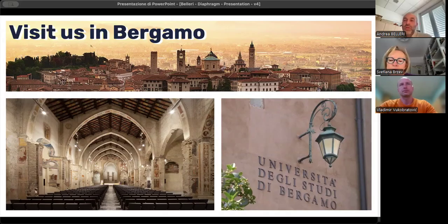Of course, yes, for sure. That was the initial plan. The initial plan was to test two specimens, one without concrete overlay and one with concrete overlay, and to test them cyclically, not just load and unload. But it was not possible for budgetary reasons. So we started with what we thought was the most vulnerable situation. It will be good to do some tests with concrete overlay. We did with concrete overlay in the small specimen that I mentioned.